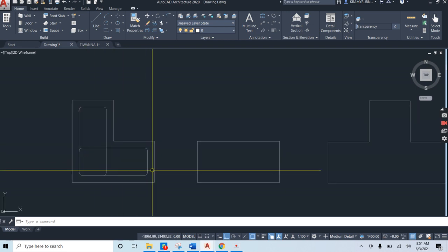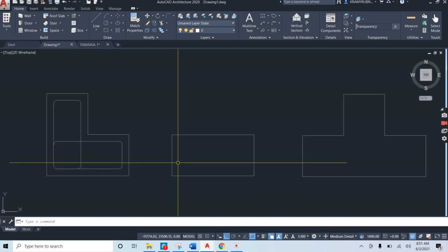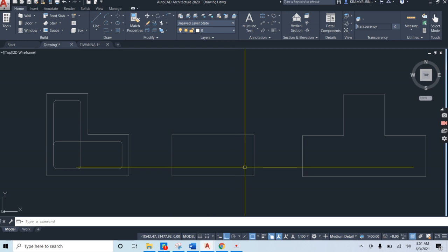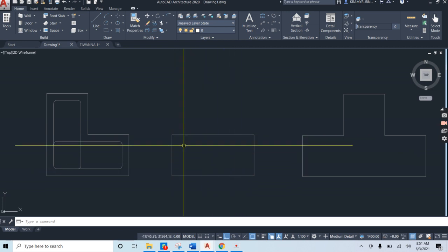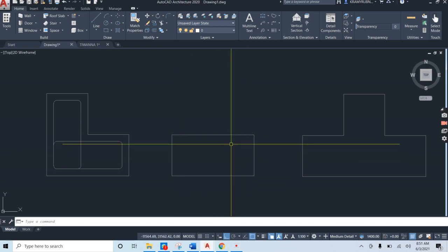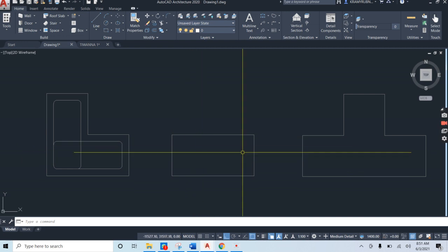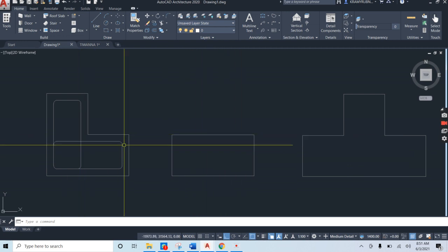Not complete, but we'll come back to that. Let us move over and do likewise for our eye stiffener. So we're going to be installing a stirrup, a link in our eye stiffener. No need to recreate, because we already have such a profile in this one.